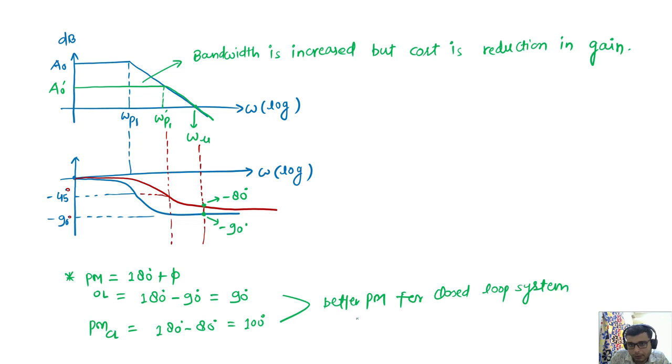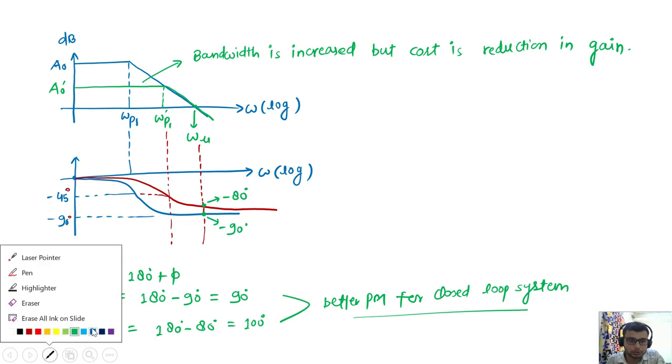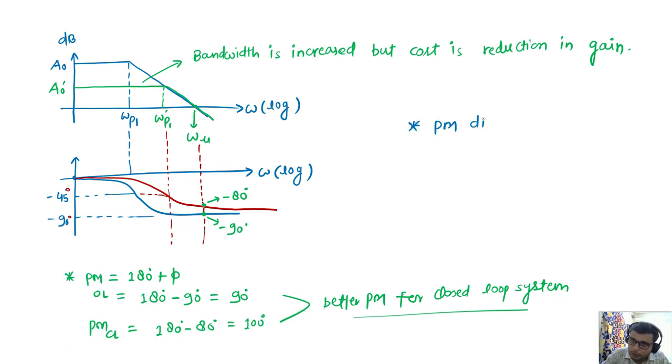This analysis is not that important, because whether open loop or closed loop, a one pole system is unconditionally stable, so there is no point in discussing the phase margin here. Phase margin will be much more important in the second order system discussion.